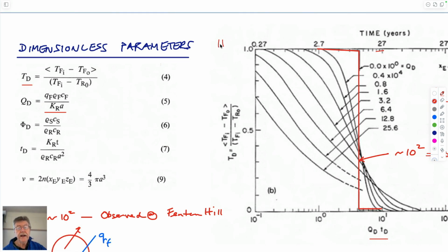This would be hot water out, and this would be cold water out. A dimensionless flow rate going through the system. We're right on the money. And also define it in terms of a dimensionless time. Dimensionless time, interestingly, comes out in terms of this thermal diffusivity for the rock. And we said that the thermal diffusivity for the rock, did we call it kappa before? We said this was equal to 30 meters squared a year.